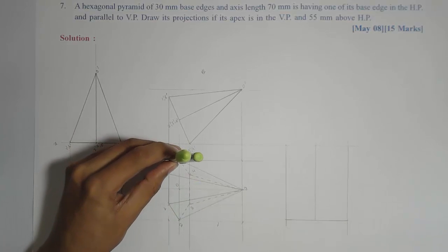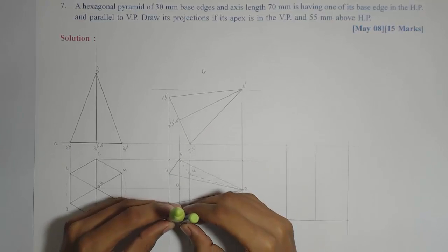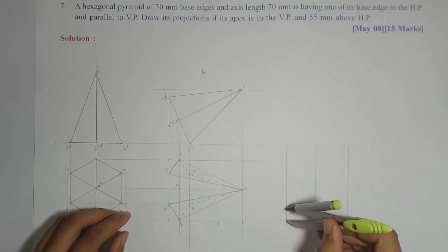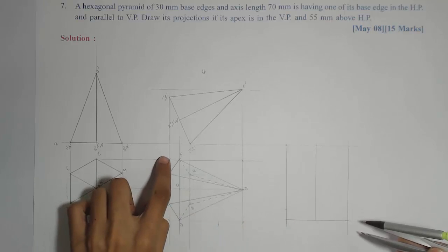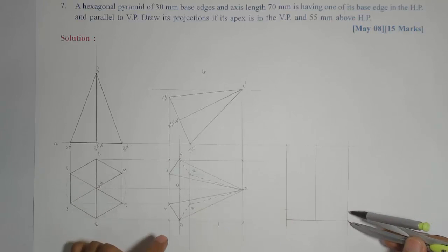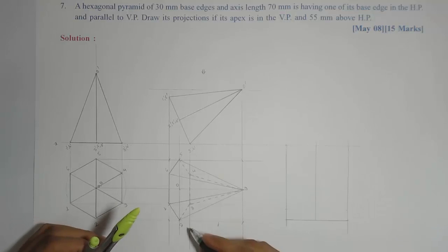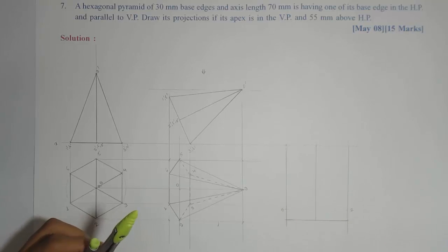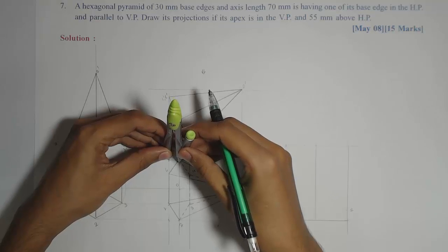So we'll mark the points accordingly. So for 5 and 2, we'll keep the same distance, and that needs to be marked from these corners, because after tilting 90 degrees, these horizontal distances will become vertical distances. So here the 2 will come here and 5 will be here. Then with the same corners we can mark 1 and 6.